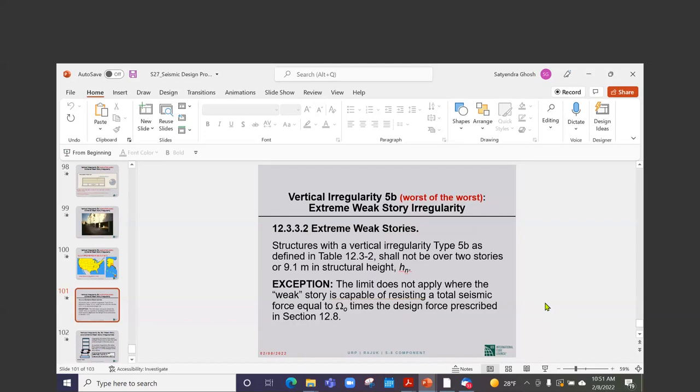So let us say a shear wall comes down on a transfer girder, which is supported by columns and so forth. So follow me closely. This is an important question. The transfer girder that receives the load of the discontinued element must be designed for the overstrength load combinations.